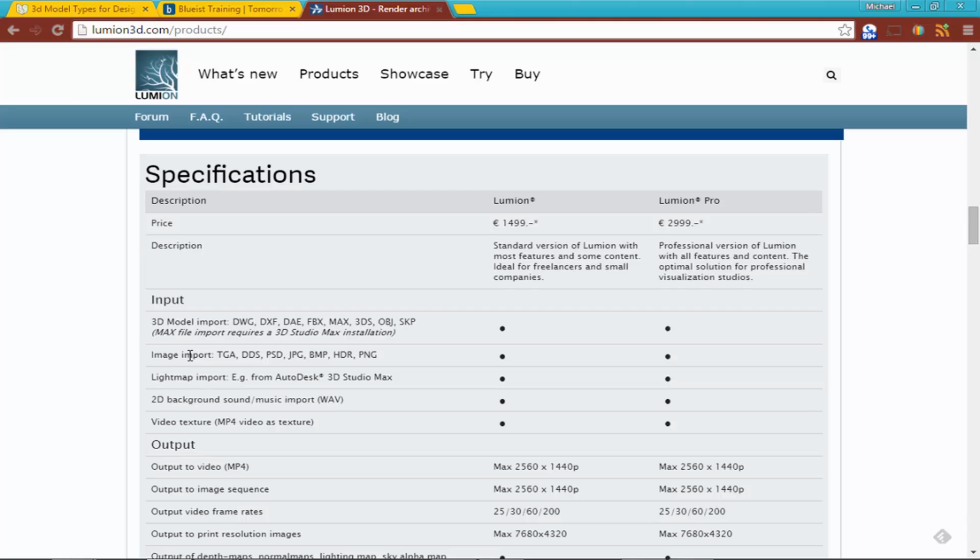These are all your native 3D file imports. And then with Revit, you've got the Revit to Lumion bridge. That's an add-on or an extra for Revit, and that'll kick out a Collada file, and that comes into Lumion. For Rhino, same deal. It's just a plugin that's optimized, that goes into Rhino and kicks out that file format that reads perfectly in Lumion.